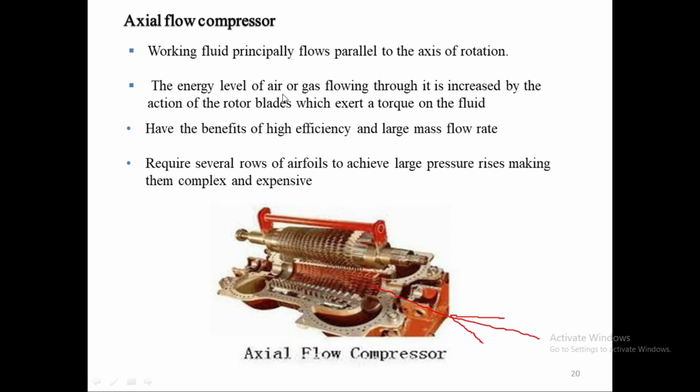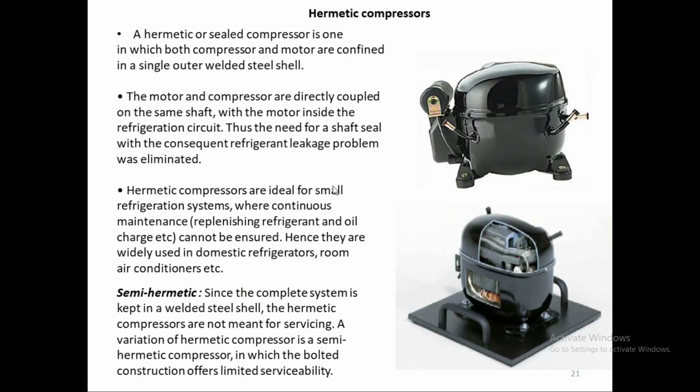Okay, so the working fluid principally flows parallel to the axis of rotation. The energy level of the air or the gas flowing through it is increased by the action of the rotor blades, which exert a torque on the fluid. They have the benefit of high efficiency and large mass flow rate, but require several rows of airfoils to achieve large pressure rise, making them complex and expensive.